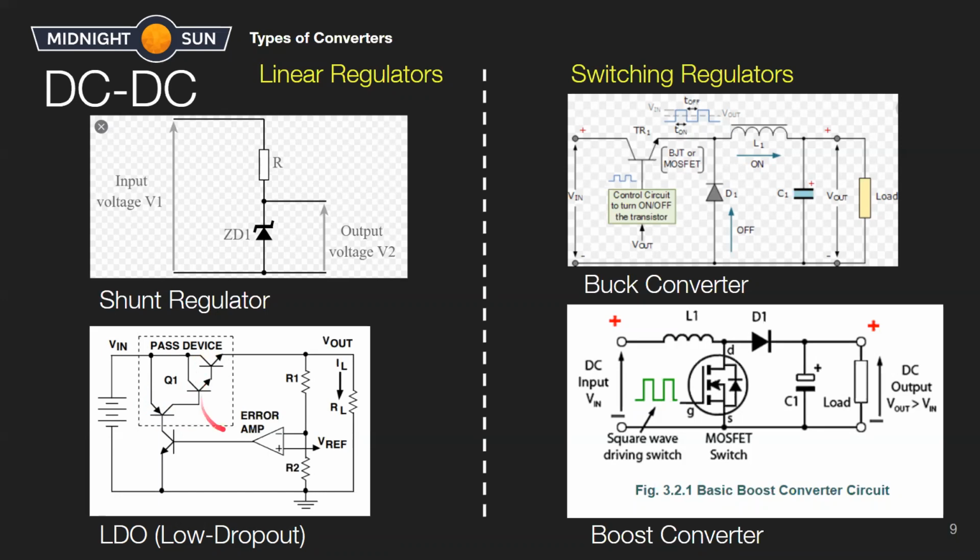So how that actually drops our load is that since we're controlling the voltage on the load, we can see that if the load is a specific resistance and we're not changing this resistance, it's fixed, right? We have a certain current that we control that goes across this load, and by controlling that current, we control the voltage that drops across it.